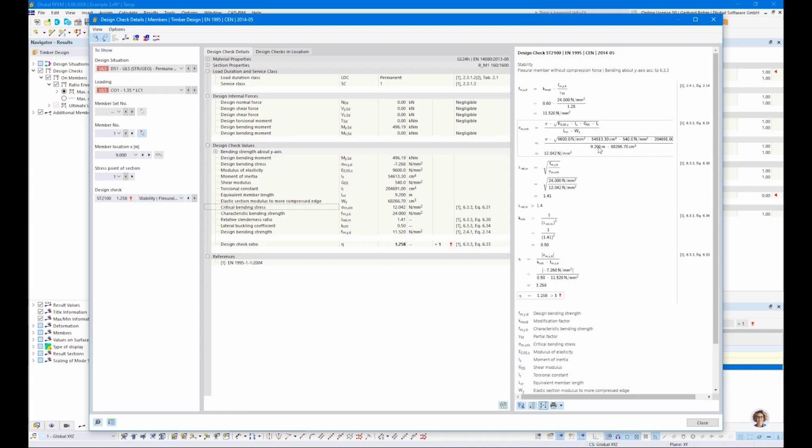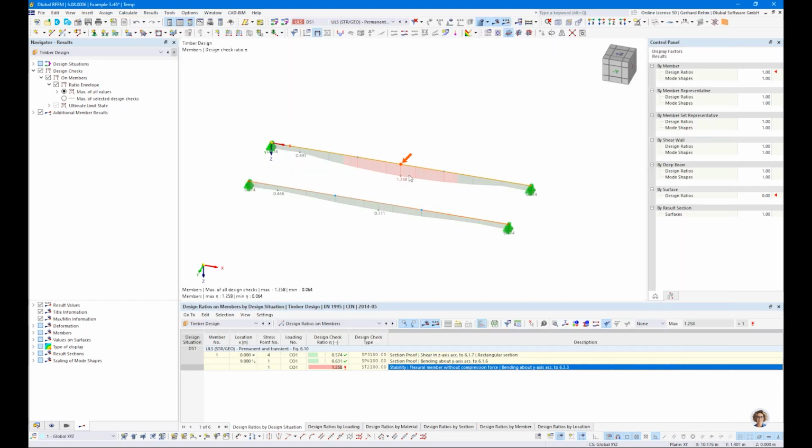It's nothing else than dividing 18 by, we have 3 spans in this case, 6 plus 2 times 1.6 meters equals 9.2 meters. So maybe this approach is not correct. The buckling length in reality is smaller. But we do not focus on this method. We focus on this eigenvalue solver method because it gives us better results.